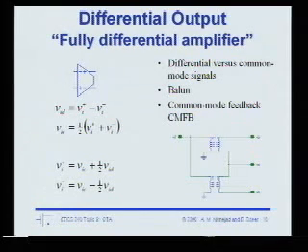The RF interfaces with the outside world, then creates a digital baseband signal, which is differential. Then you have several differential stages of amplification and filtering, and then you have a digitization process. So you never have to worry about this issue if you're designing integrated circuits. Designing circuits that interface with the outside world, then you need some stages that do conversion for you.